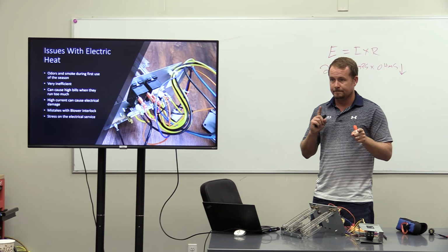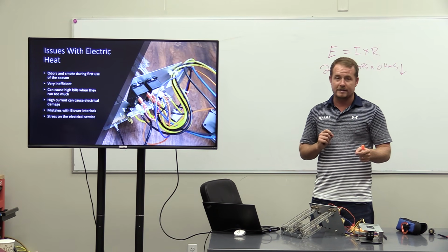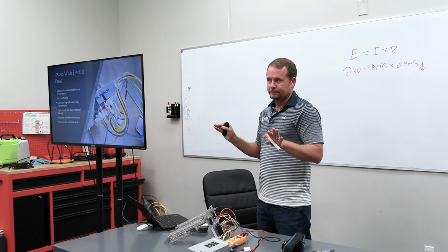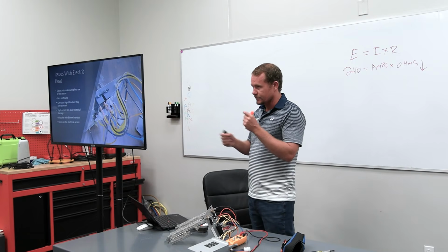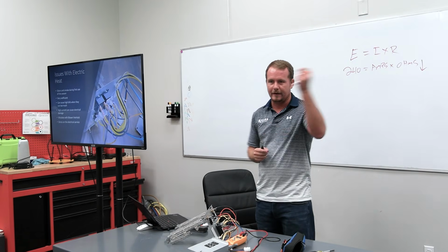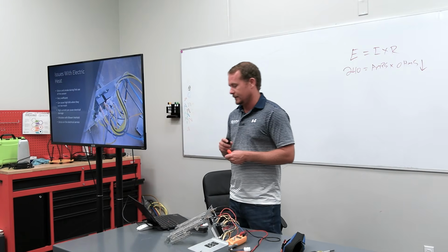Make sense? Just a quick poll: 20 amps, what size wire does that need to be, typically? Number 12 wire, right? Typically, that's the size wire you would use. Now there are some exceptions to that rule, like we talked about in a class we did recently on wire sizing. But generally speaking, that's what we're looking for.